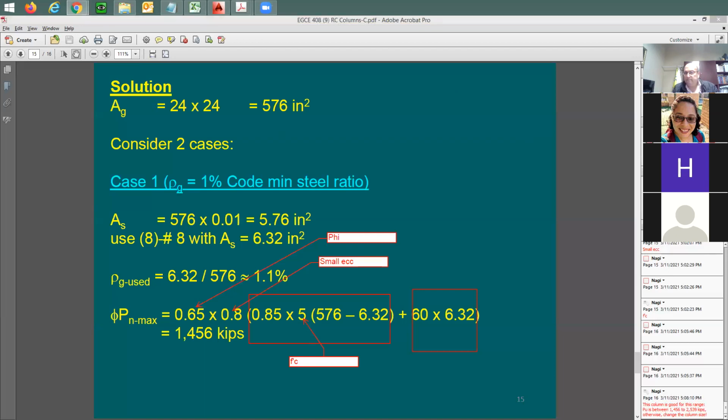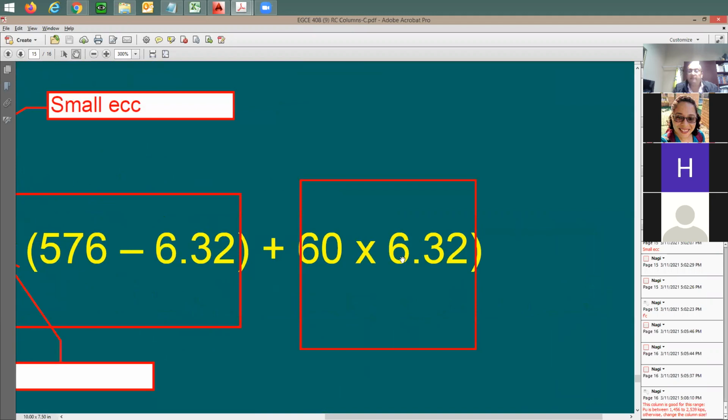So do we not account for the area of the steel in compressive reinforcement in our beams because it's so much smaller? No, we account for it. Look at this. It's right here. No, I mean in our beams, when we had compressive reinforcement. Oh, yeah, we ignore the steel in the top. Generally speaking, we try to ignore it in the beginning.